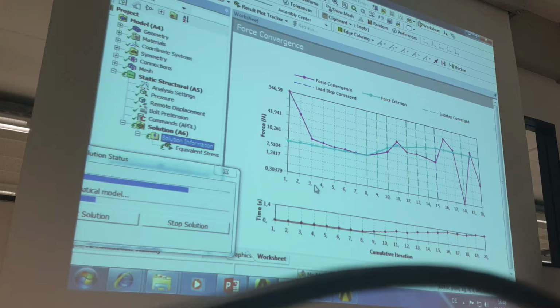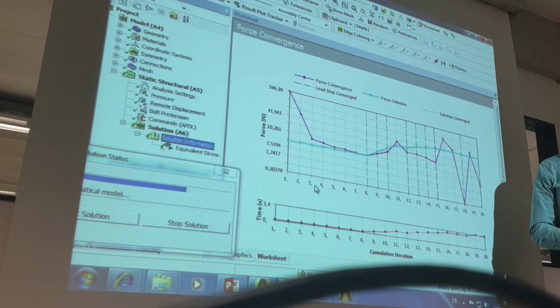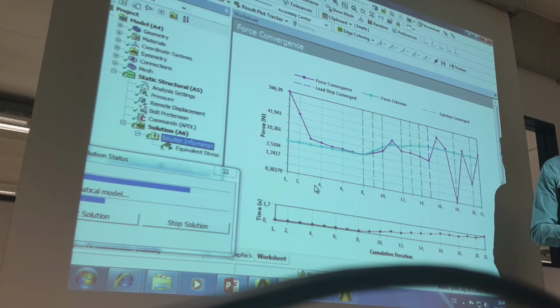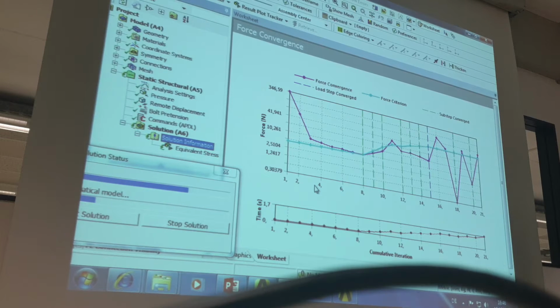Yes, how many loads? For example, it works like this: the customer gives us information that this part has to work 150,000 times with this much pressure, yes, and we have to check it. So then we simulate it and we try to do that with the same safety, I don't know, 20%, 50% safety, works 150,000 times. Then we are doing tests, and if nothing is broken, then everything is okay. Then everybody is happy, simulation says it's okay, measurements told it's okay, and then everything is okay. So, okay.